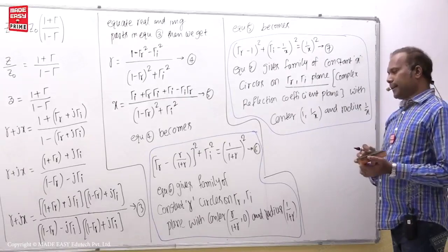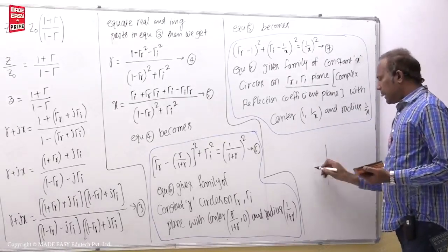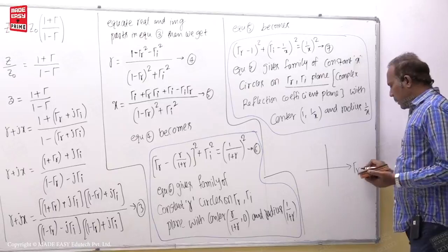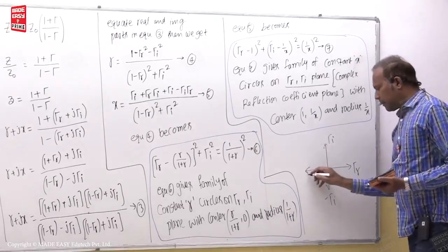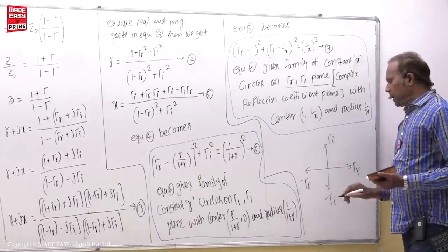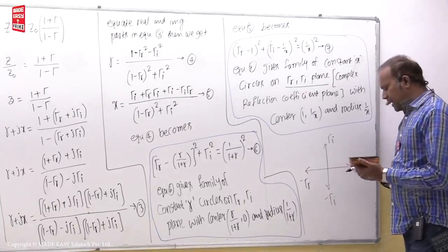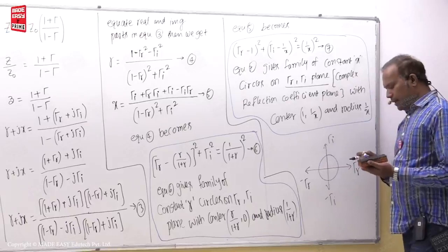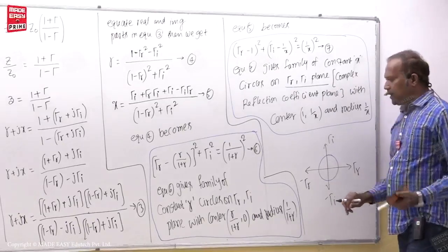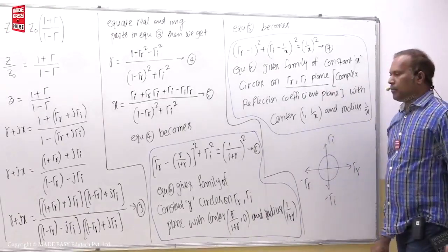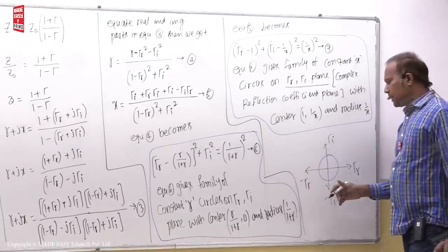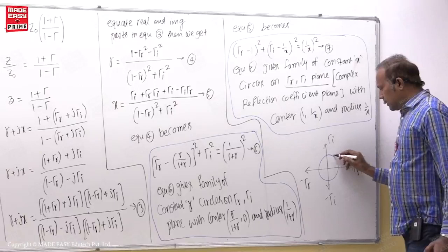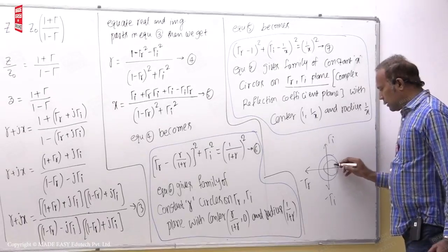So what is Smith chart? You take the gamma r and gamma I and minus gamma I, minus gamma r here. Then the biggest circle is the unity circle, and inside that unity circle you draw the constant r circles. Then they come like this, this one, this one, this one.